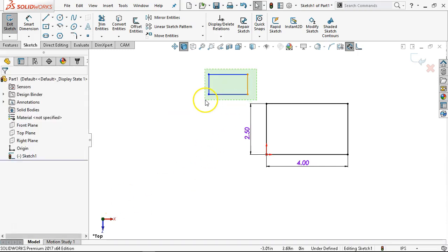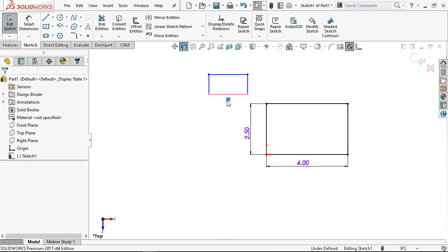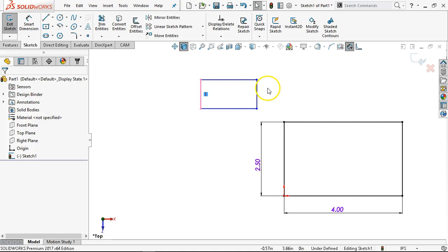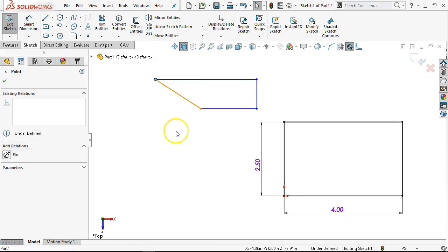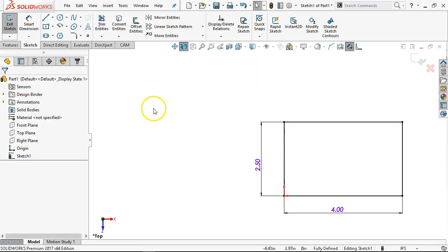since the objects are going to infer relations. The inference is that when you draw a rectangle, you will get 2 horizontals, 2 verticals. And then at any particular time, if I decide that I want to manipulate, I can delete one relation and make it a little bit off. I can change the angle, I can get those 4 lines in, get that geometry in, and then shift it pretty quickly.